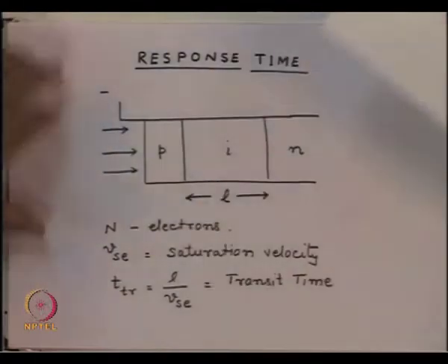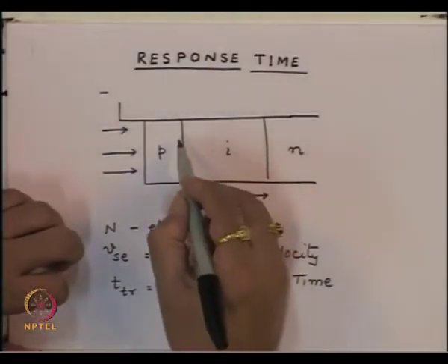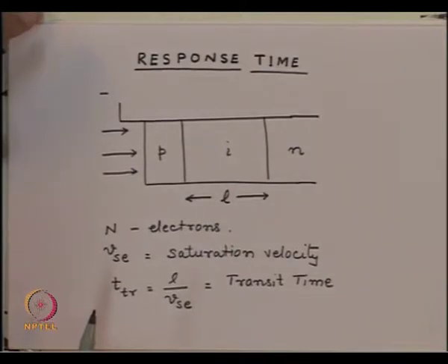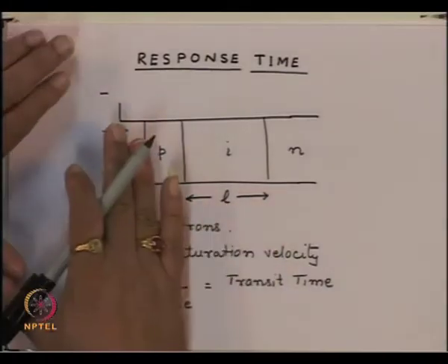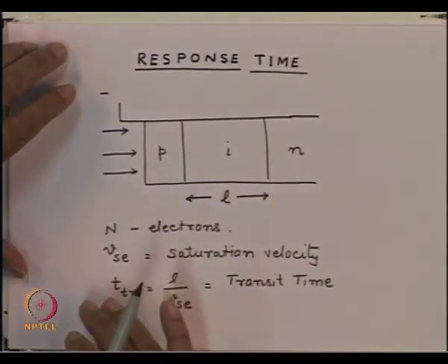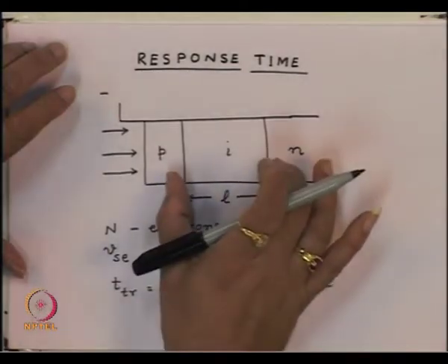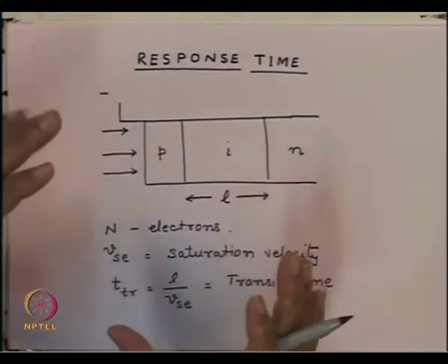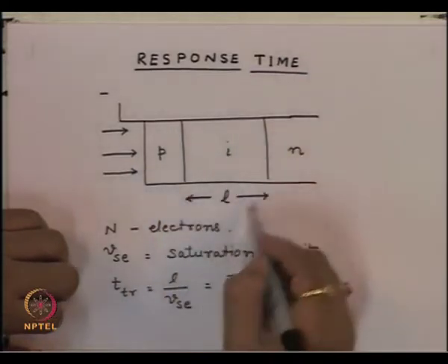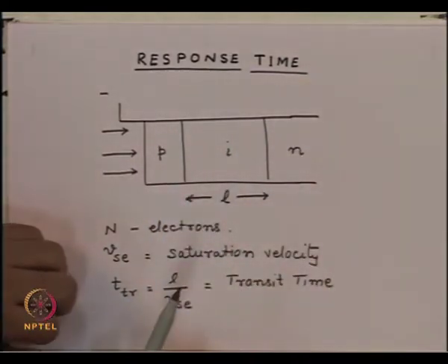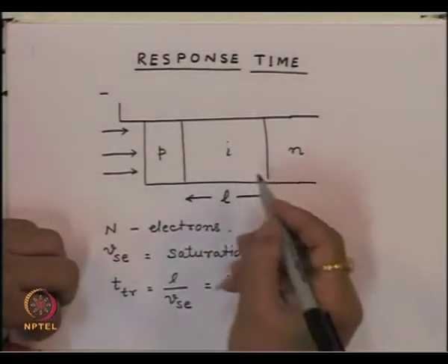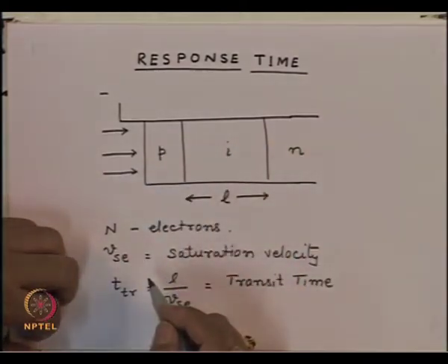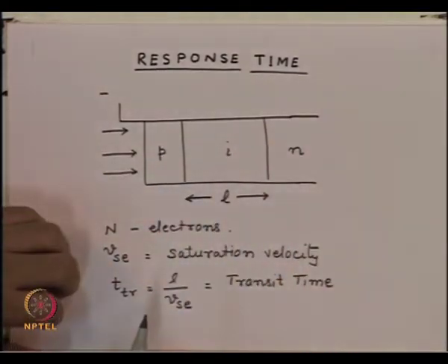Most of the time, we will see that the electron hole pair generation takes place almost over the entire region. So, let us say that when the light propagates inside this material, the time over which the electron hole pairs are generated is very, very short. So, the entire region essentially gets filled almost instantaneously with the electron hole pairs. And then electrons will start moving in this direction, holes will start moving in this direction. So, we will have a combination of the currents flowing in the external circuitry because of electrons and holes.